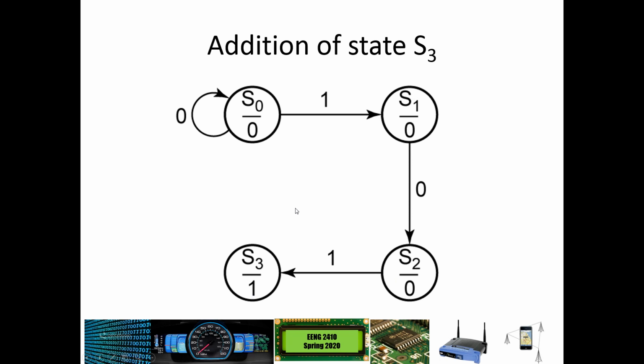And so now what's left to do, because this is incomplete, is to fill in all of our other transitions. So right now we have both a 0 and a 1 transition for S0. We have a 0 transition for S1. We need to figure out what we're going to do if we're in S1 and we get another 1. That will be very similar to what we did in the Mealy circuit. In fact, we will have it exactly the same. It will just transition back to itself.